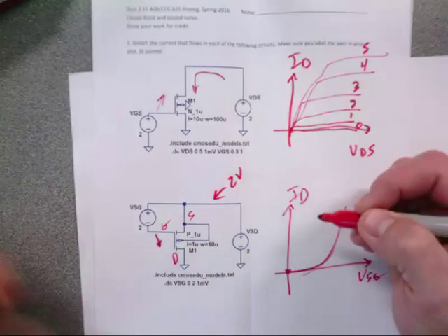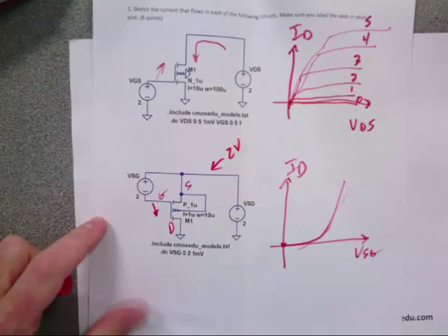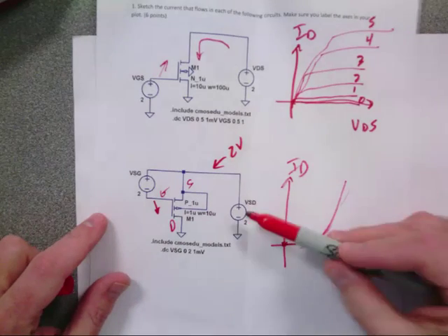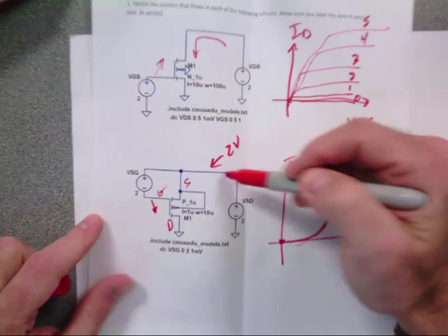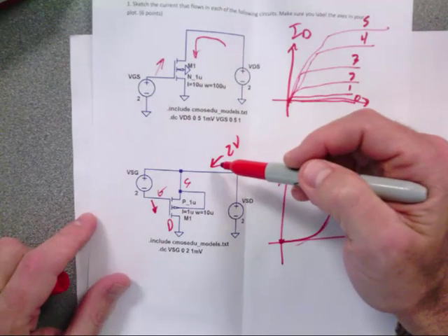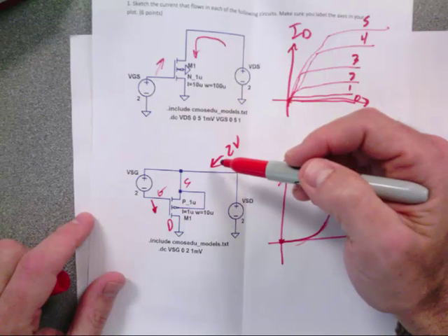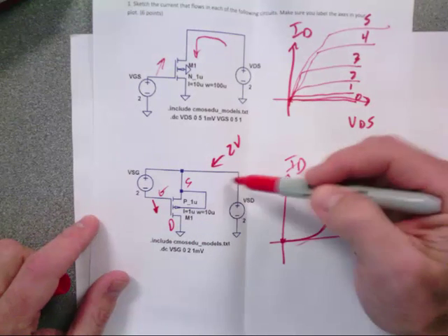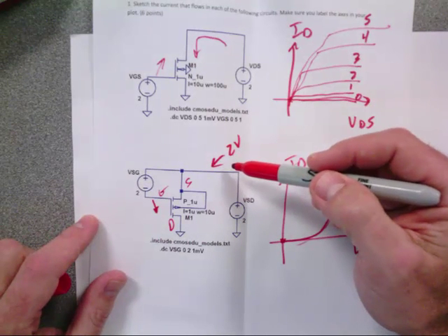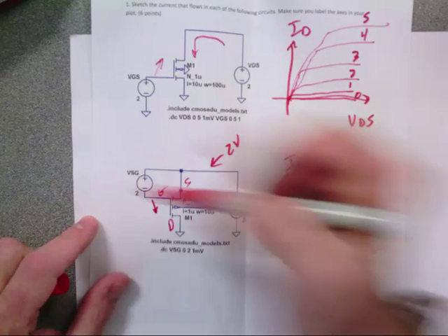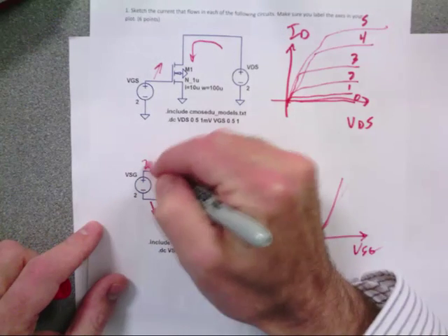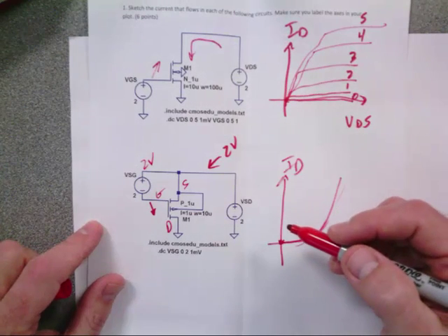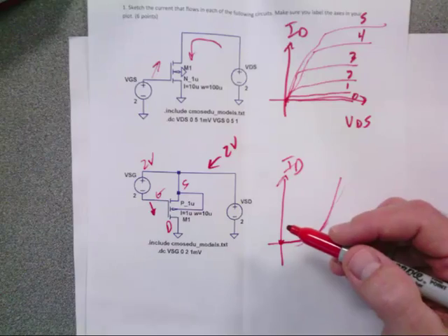Anybody not see? Okay, when you are looking at a schematic and you see a voltage source to ground and somebody asks you what the voltage is at that node, you do not expend brain power. Your brain locks in 2 volts, and if they argue with you, you point to the voltage source connected to the node. Okay? When I see plus minus, if this is 2 volts, that means I'm dropping in potential. Means I'm going downhill.